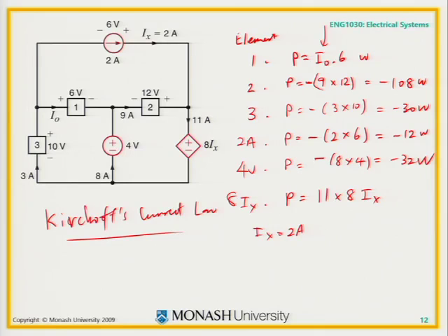And what this says is that if you look at any interconnection point between elements, then the sum of the currents must be equal to 0, as in the sum of all the currents coming in must be equal to 0, or the sum of all the currents going out must be 0. So if we look at I0 and the current coming into this, what we call node, you've got 3 amps here and you've got 2 amps coming out here. Well, simply this must mean that this must be 1 amp when we sum them all together.